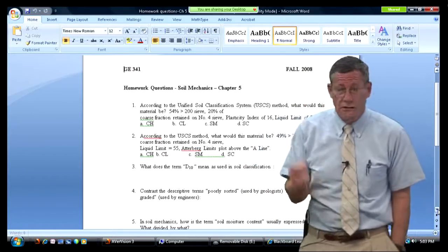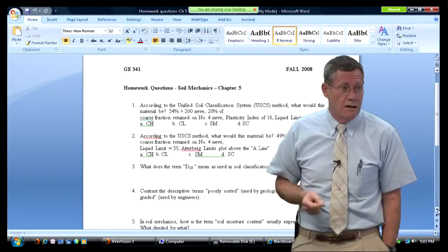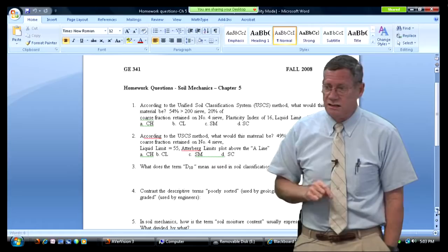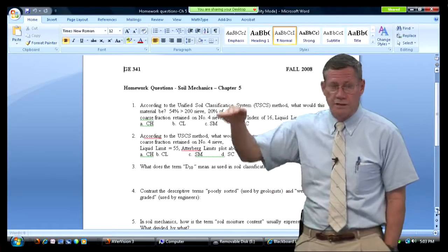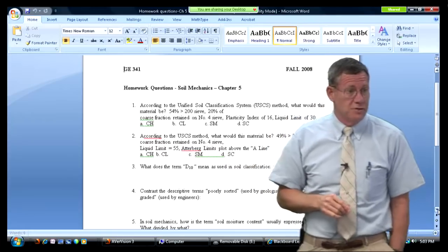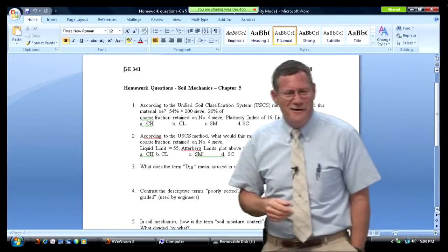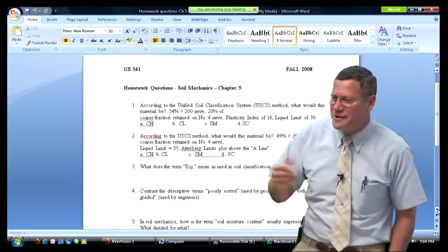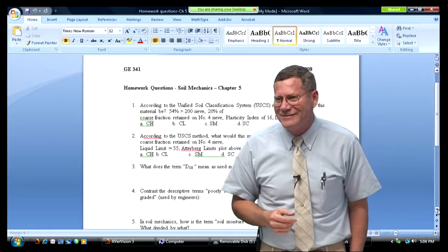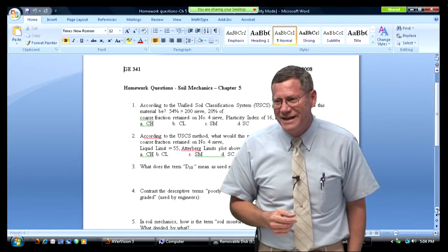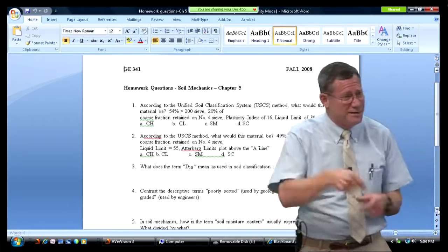It was all real fine-grained granitic sand. All same size. Very fine, no cohesion. And they made a levee out of it. The locals call them sugar levees. I said, why do you call them sugar levees? Does something sweet grow on them? No, when you put water against them, they disappear like sugar in hot water. Wow. Hell of a dam, huh? It's like that stuff you give your kids, you put it in the tub and it disappears.